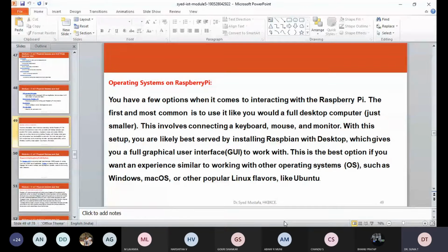When we are going to format the SD card, care should be taken before copying the NOOBS onto it. Download SD Formatter 4.0 from the SD Association website for either Windows or Mac. Follow the instructions to install the software. Insert the SD card into the computer or laptop SD card reader and make a note of the drive letter allocated to it. In SD Card Formatter, select the drive letter the SD card is in and format it.